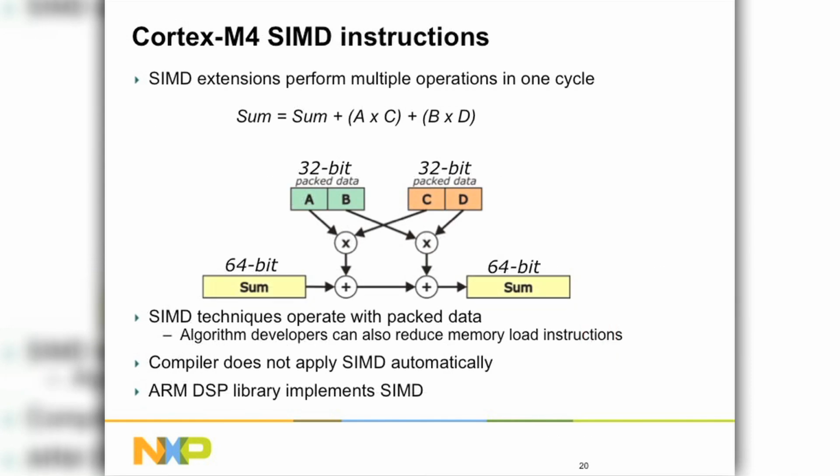So SIMD, single instruction, multiple data. The floating point unit can be used by the C compiler, but SIMD is a little less friendly with C compilers. So we tend to see the benefits of SIMD with people who are writing optimized libraries, or if you wanted to do things like a stereo channel where you take 1 instruction and execute it on 2 sets of data. Anyway, the instructions are built into the core, and are one of the things added from M3 to M4.